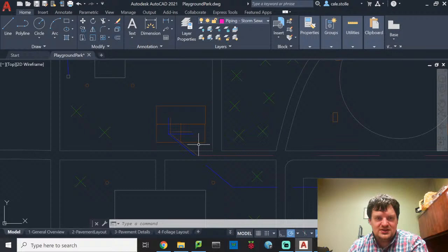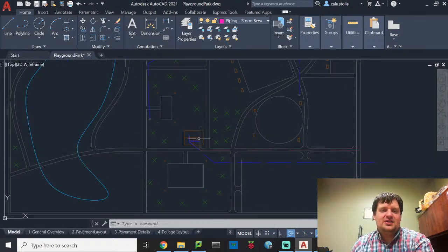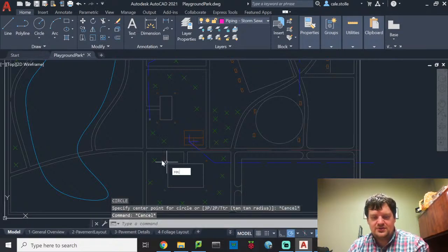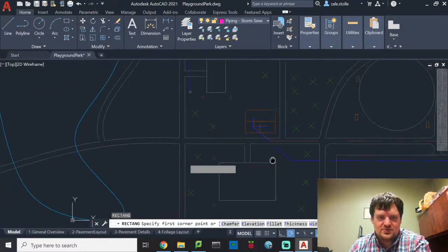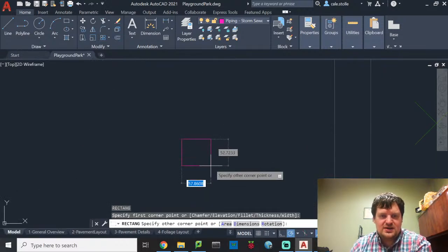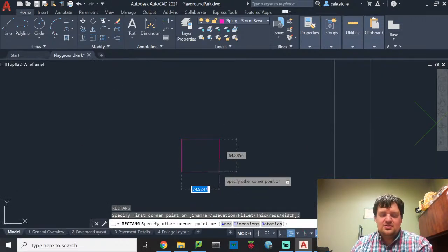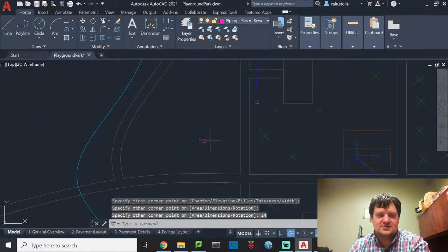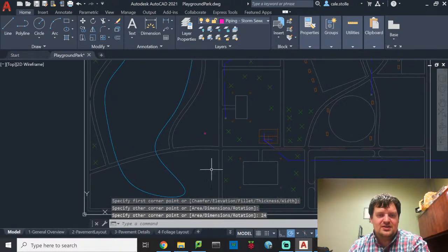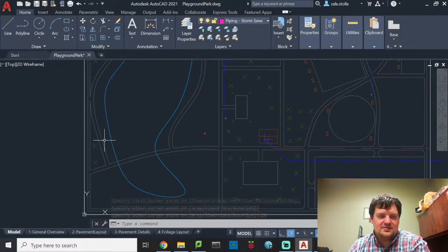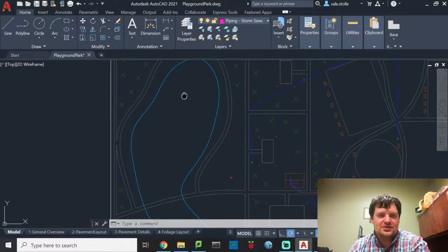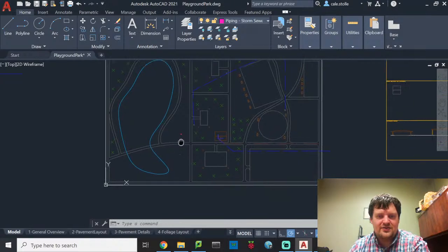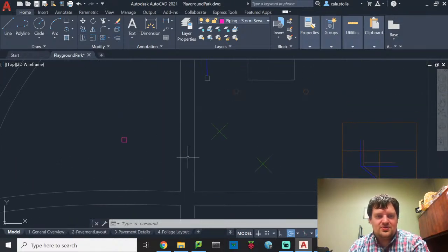With the storm sewer, basically what we're going to identify here is I'm going to create a rectangle. We'll use a very specific kind of storm grate. Those storm grates, we'll have them be 2 foot by 2 foot again, just because that's about the size of a storm grate. Now here, all the water that's going to be running off into this lake, I don't want that to go into a storm sewer. So this whole area right here, I'm not going to have any drainage for.